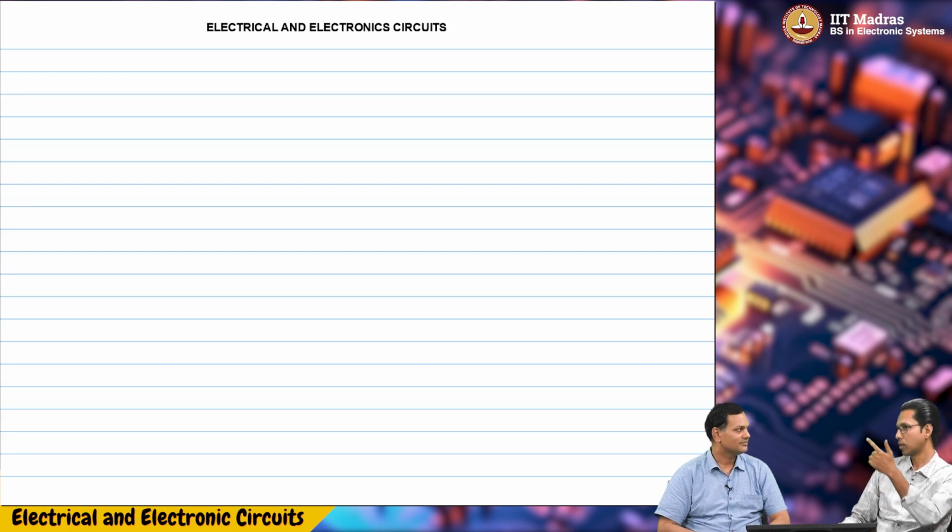In most of our circuits where L, C, etc. are present, for example, current through the capacitor is C dV by dt. Voltage across inductor is L di by dt, and so on. So there is a derivative always. Correct. That's true. So if you have some i of t, you will have to take the derivative of that function. So how to deal with that in the S domain? Or somehow we have to represent that.